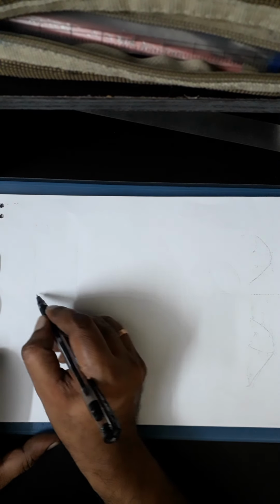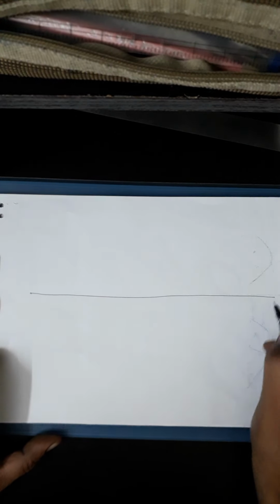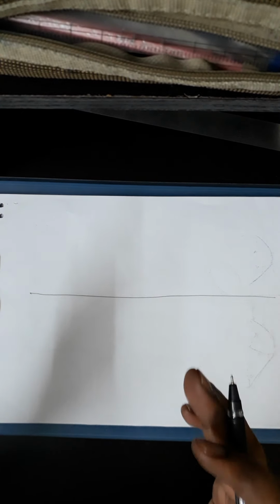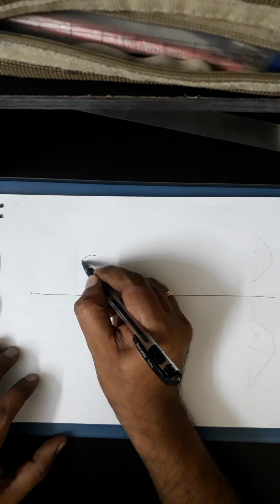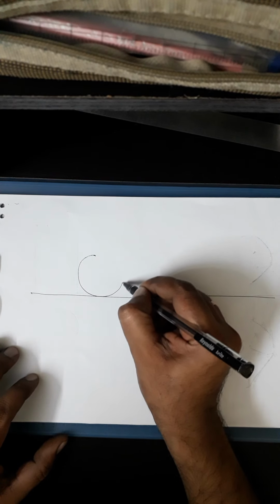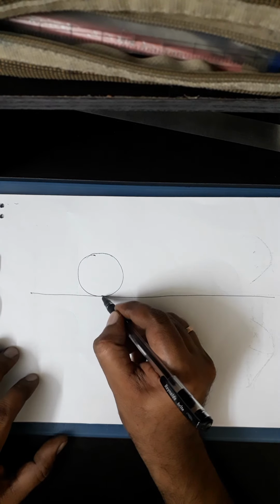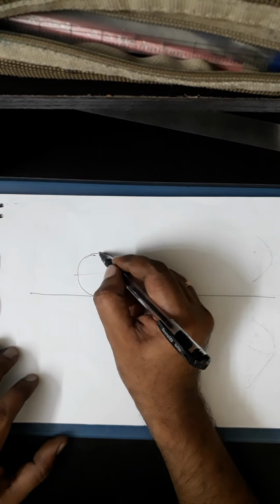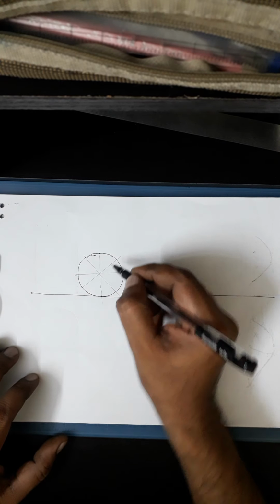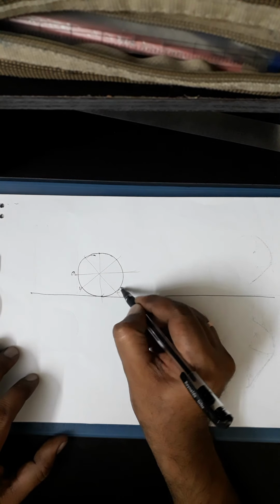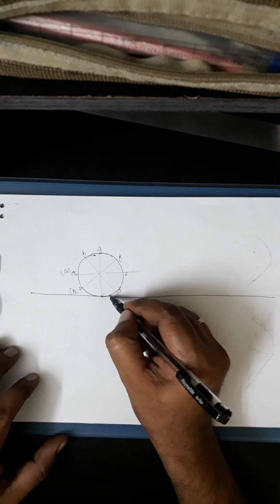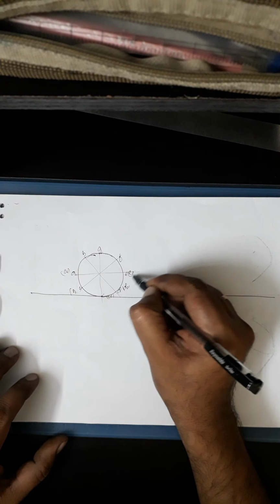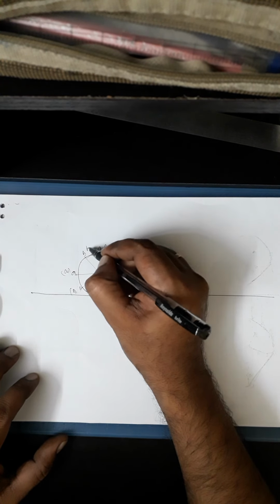Otherwise, you're going to have a problem where it says it is resting on one of its longer edges on HP, so one of its end generators on HP. In that case, similar to the longer edge resting on HP in case of prisms, you can go for directly drawing the circle in VP. So in that case, if you take this, divide it into, say, I'll just divide only 8 parts, but I want you to divide that into 12. So A, B, C, D, E, F, G, H. So this is say A1, B1, C1, D1, E1, F1, G1 and H1.